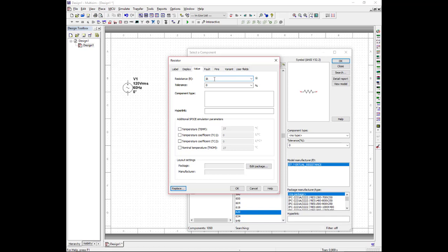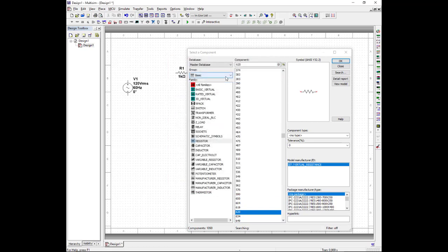Right, and there's no need to put in the ohm symbol; it already exists over here. So once I've entered that, I can hit the enter or return key on the keyboard or click OK on the image. You can see I've changed to a 1K resistor here. And again, my component window popped open for me to select something else.